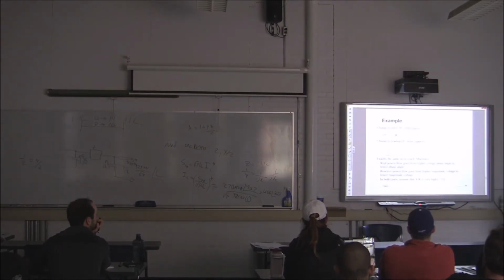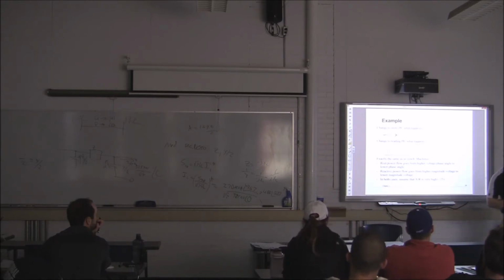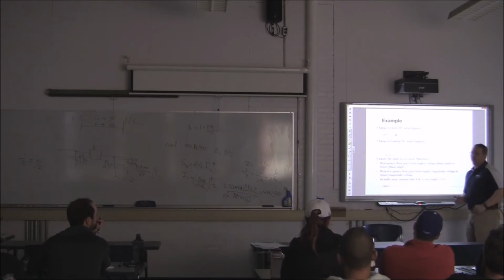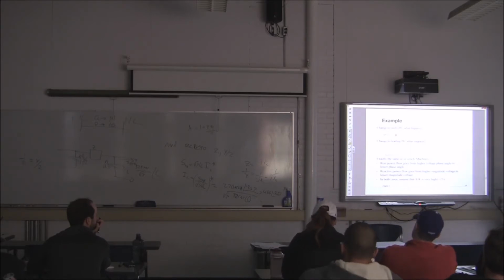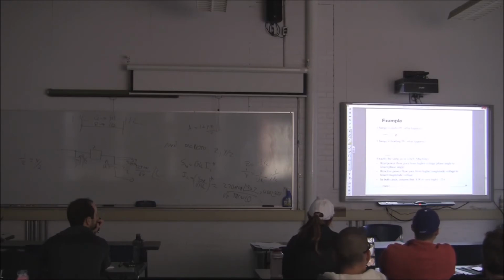We still have a magnitude of IR, which means that there's current going through, which means there has to be real power flow, because it's a unity power factor. So power is going from the sending end to the receiving end. That does not change. Okay? And in the case of a leading power factor, what does that tell us about the load? It is more capacitive than inductive. And we say capacitors supply reactive power, inductors consume it. So keep that in the back of your minds.